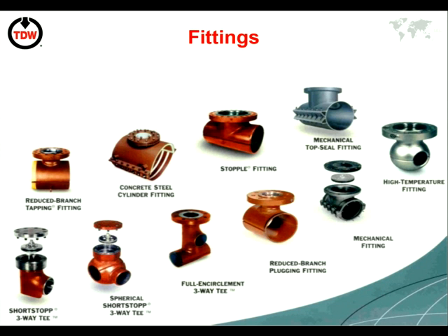So there's various options of doing this, depending on the requirements, but typically the vast majority of them is this, which is just a welded fitting. So it's a shell fitting which goes over the pipeline, and it is welded and sealed. And obviously this area here is where the tapping will go through, and I'll come on and show that in a little bit more detail.